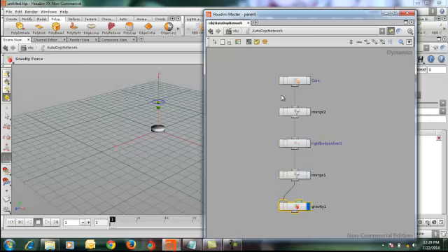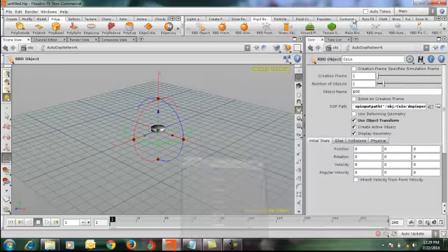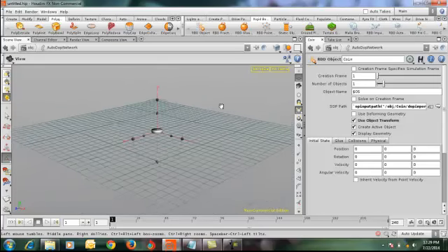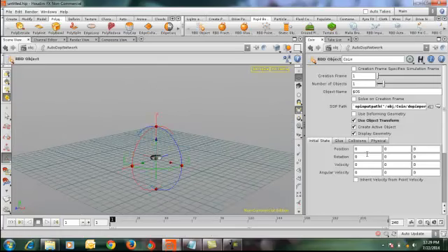Now click on this coin here and let us see the properties that we have. You've got position, you've got rotation, velocity, angular velocity. We're going to keep these more or less, but we're going to change the position and rotation as we go ahead. Creation frame and number of objects. Basically what number of objects means is how many objects you want onto the scene. You can have multiple copies of the same coin object. At the same time, creation frame tells you in which frame the new rigid body object is going to get created.